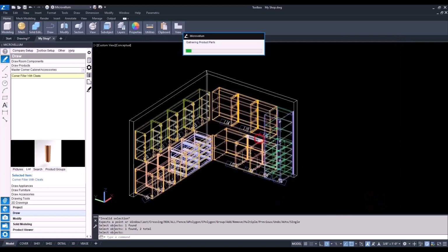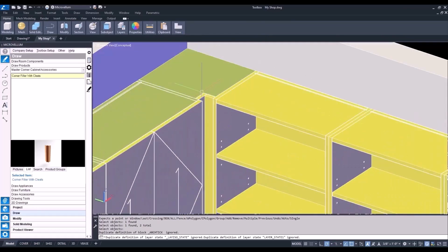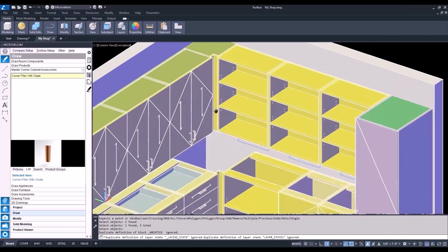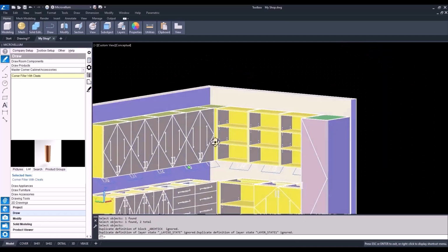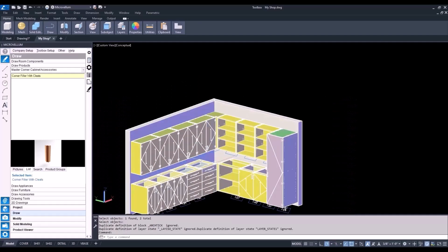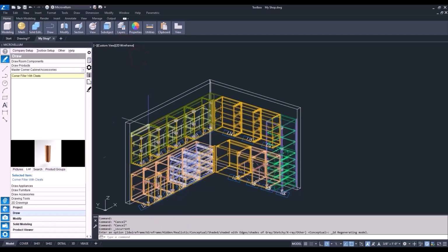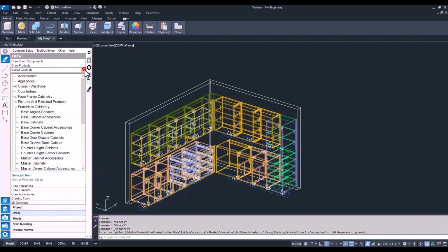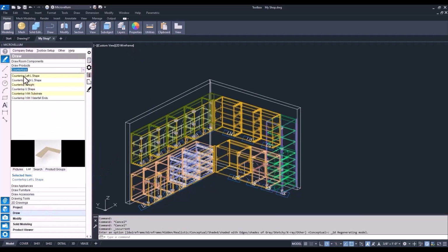And then just going through our prompts again into the construction options, making sure we have our top and bottom returns on. Now we have our top return. Check out our bottom return. Now in this situation, I didn't need to worry about turning on that finished bottom prompt. All the upper bottoms are using that plywood material, whether or not we have them called out as finished or not. So what it's doing, it's basically coming in from what we have set up in our material file to figure out what material needs to be used on that bottom.